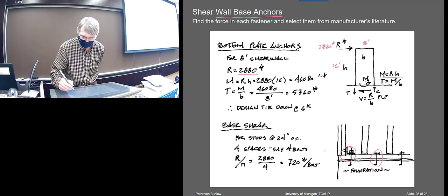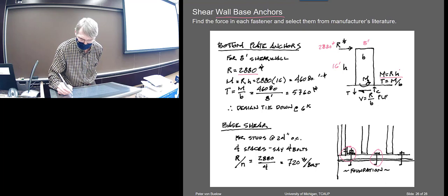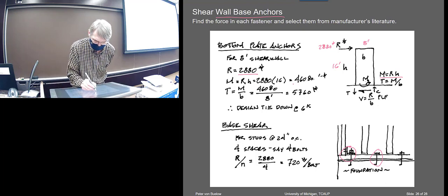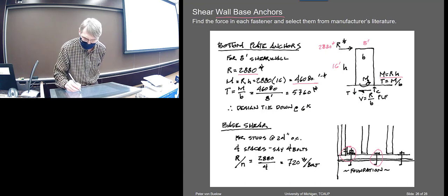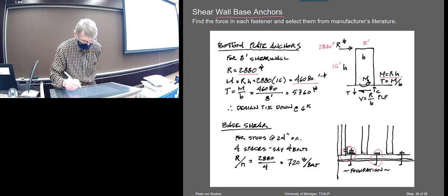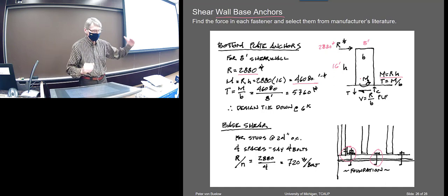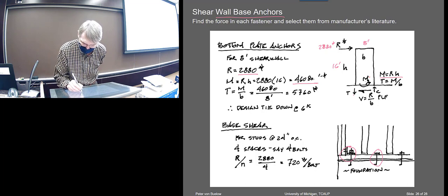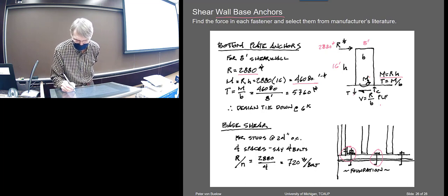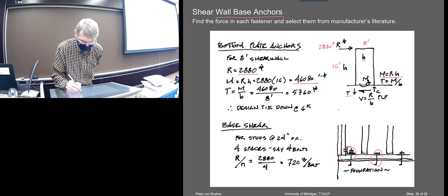force as a cantilever, right? And that comes out to this. And then I want to calculate, that'll be the same moment, right? That has to be resisted, it's the exact same moment down here, resisted by these two, that couple. So we take the tension times the width 8.